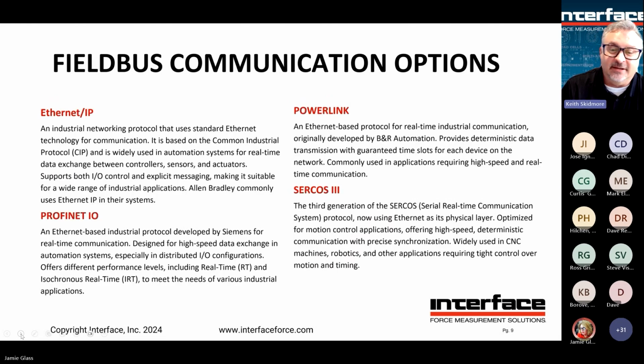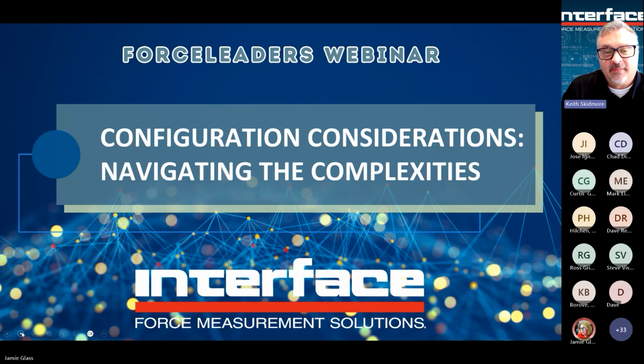Next slide. Even more options. Again, like I said, if you're going to pick one, say you're going to go digital, something like RS-485 ASCII would be quite easy to use. Certain ones are pretty easy for anybody, and some of them require, say, an expert. So if you have an EtherNet/IP network, you need people who actually know how to program and set things up on that network. Next slide.